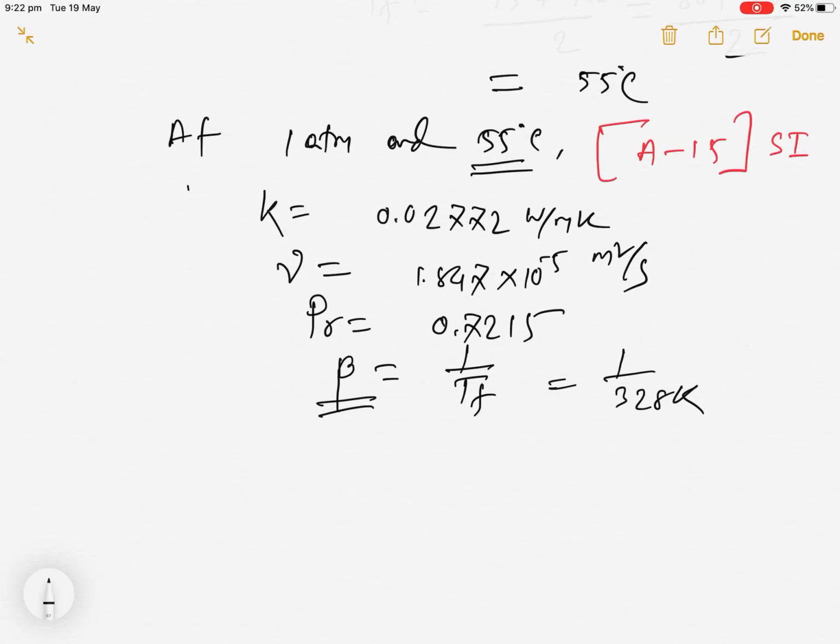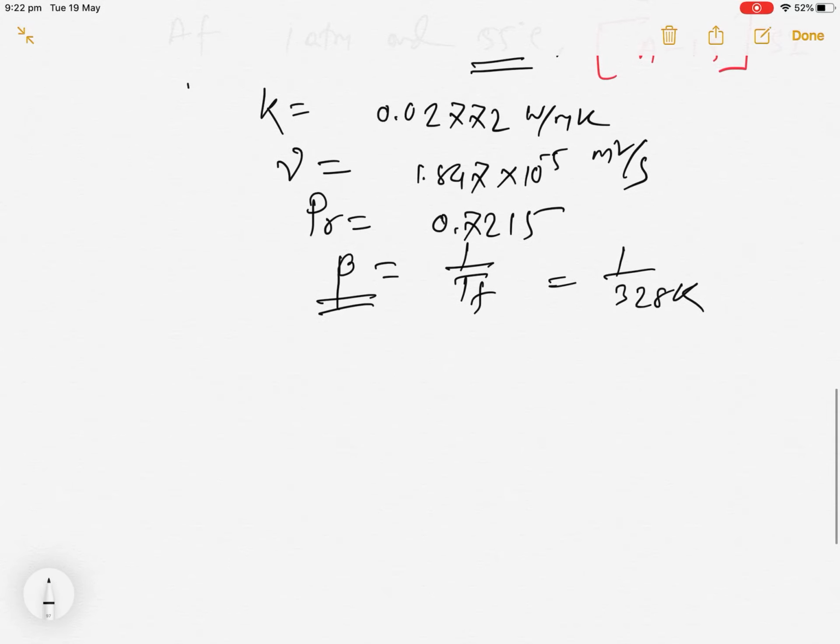Here, actually, what we will do now is start with the analysis. As we discussed during the lecture, for rectangular fins, the characteristic length we can consider to be the length of the fins in the vertical direction, as we do not know the spacing.